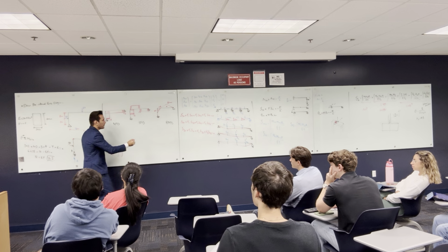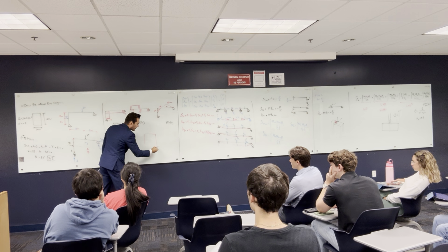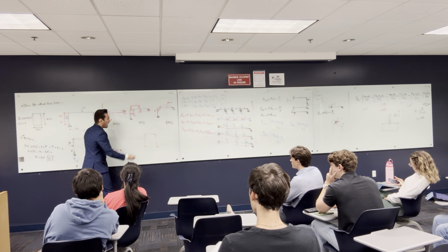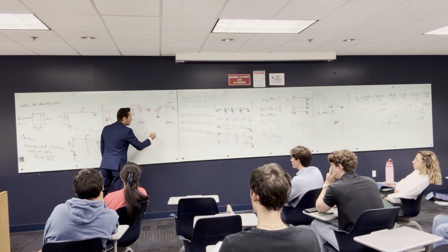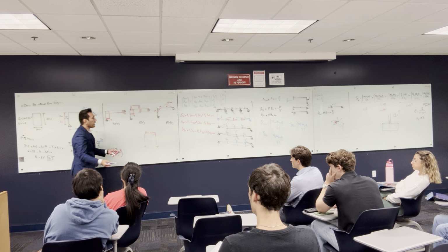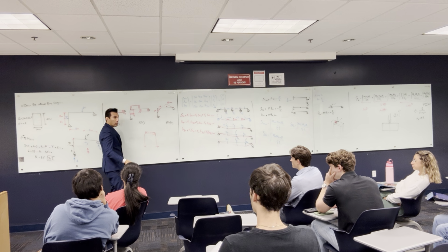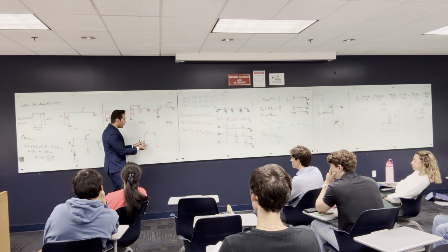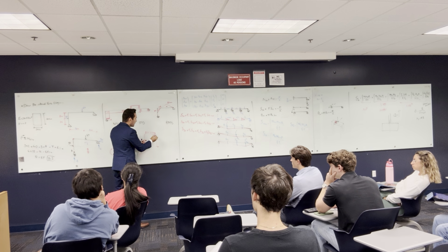If I have an indeterminate section like this, and a bunch of loads, let's say it has this load, I don't have to get numbers, but I have to have imagination. What does the final bending moment look like? You should know that. For example, this one gives me a bending moment like this here, something like this.